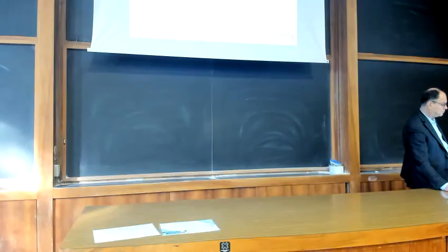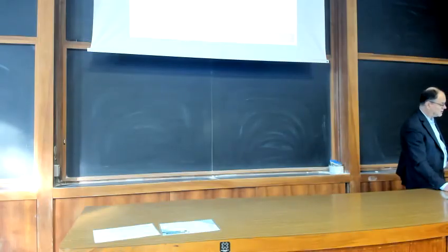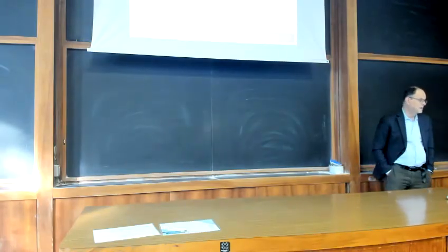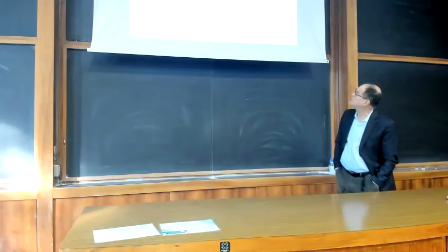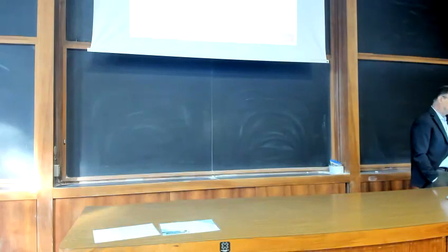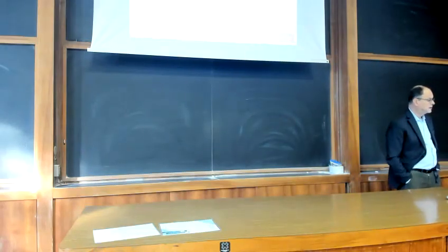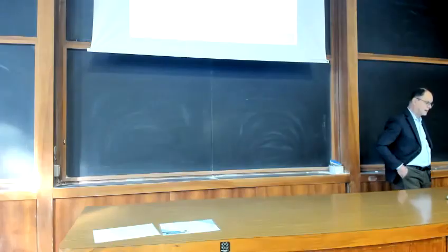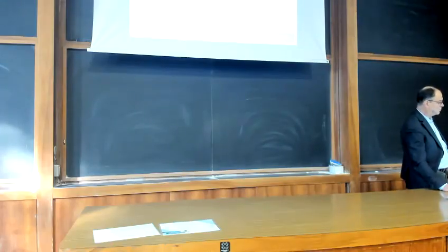Expressed in terms of effective stress analysis, for a cohesionless soil, it says that the maximum tangential stress is proportional to the normal effective stress on the failure plane times tangent of phi, where phi is the angle highlighted here in the Mohr-Coulomb plane.